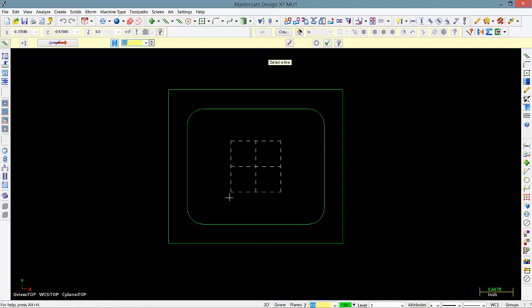So the first point we're going to locate is down here, and we're going to do a distance of 0.875. So there. And then I'm going to apply that. And then I can click here and click arbitrary up, and we'll make this one 1.0. I'm going to hit apply. So there's my first center point that I'm going to use.